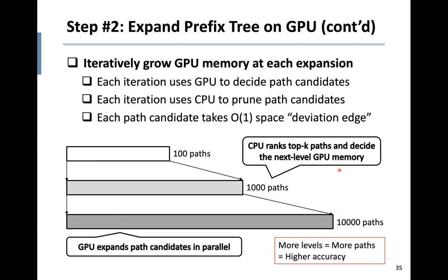And this process is the key part in our algorithm. One challenge here is the dynamic GPU memory access. Each level will expand another new set of paths, and we have no idea about the exact number of paths that will be generated at each level. For a general graph, the number can go exponentially. But for most circuit graphs, like I said, the degree is not going to go beyond 10 or 12. So we can properly control the expansion size at each level.